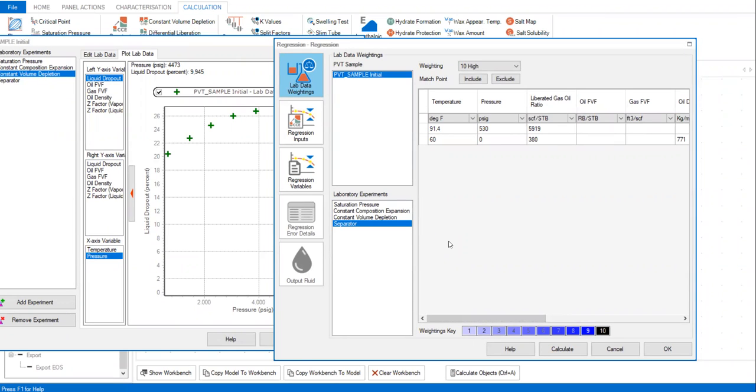At this stage, we need to already have a good or relatively good match for the first stage GOR and liquid phase density for the oil. If indeed you have, and of course right now we have a relatively good match for the GOR and the density, we can use these two values as anchor points. Why do we need the anchor point?